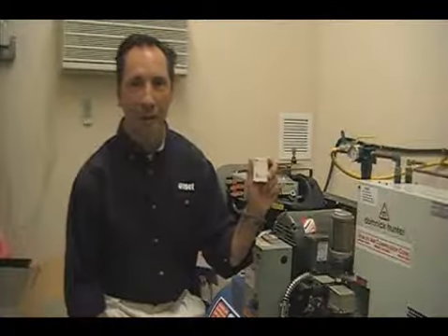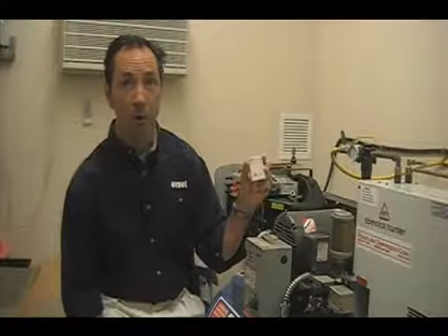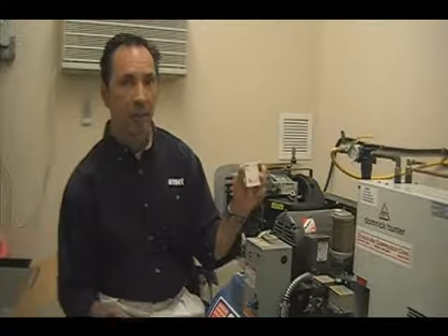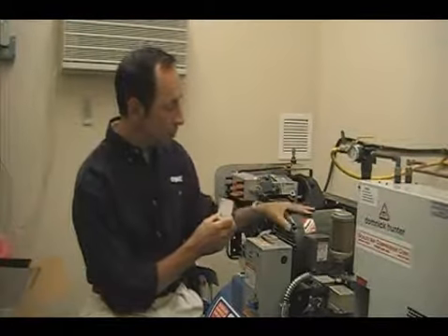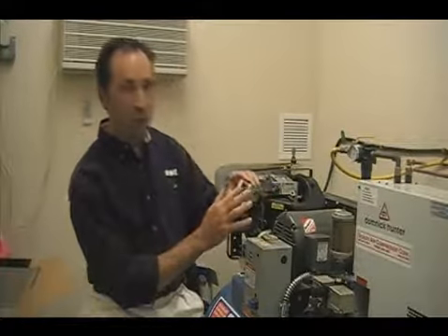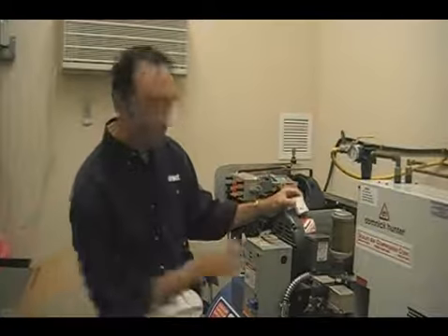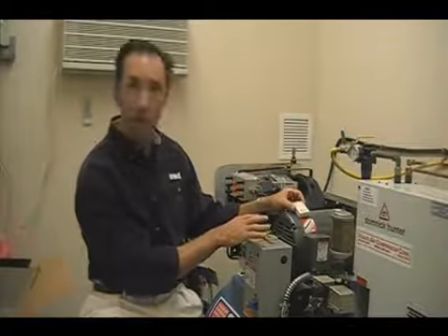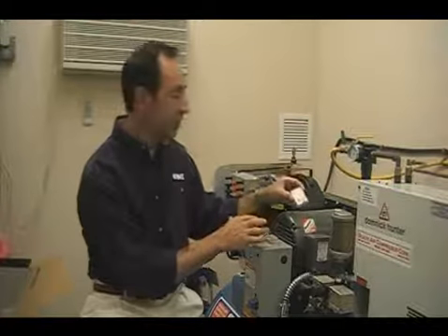Now that we have our U9004 HOBO motor on-off data logger launched, we're ready to install it in the application. Today we're going to install it on this compressor, and specifically on the AC motor on the compressor. Because the AC motor has a steel housing, we're going to use the magnetic mount to attach it. And we have to attach it as close as possible to the place on the motor where the coil is. That's where it gives off the magnetic field that this logger can detect.